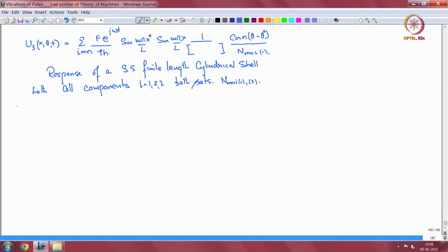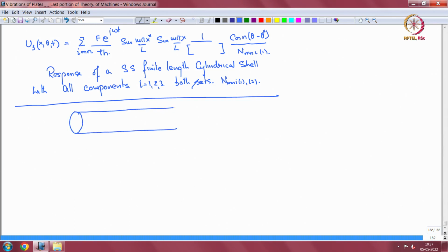Now this is quite cumbersome every time, quite lengthy. In many shells, let us say the aspect ratio is very long, that means the length is much longer than the diameter, then it turns out that in the transverse or u3 direction the shell is very flexible, and still stiff in axial direction and torsion.